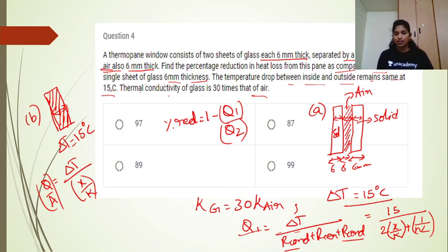Which means, okay, here they have given that it is stagnant air, right? So what is the difference between stagnant air and convection? In stagnant air, there is no movement of the gas molecules, right? So as there is no movement of gas molecules, we shouldn't consider the heat transfer mechanism through the air as convection. It is through conduction. So here also X by K of air. It should be X of air by K of air. So it is not through convection.